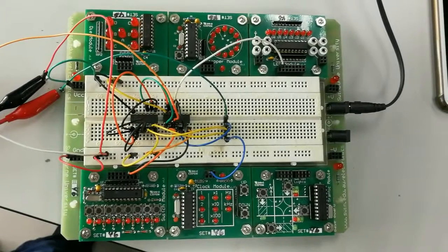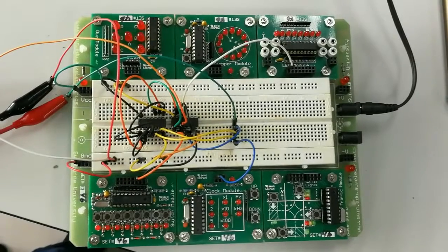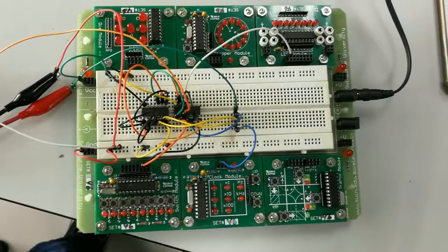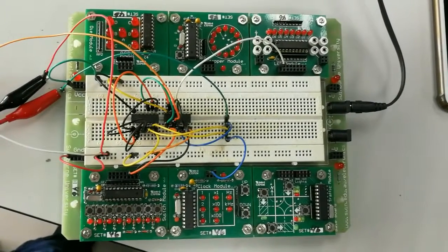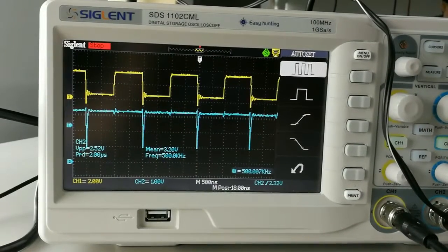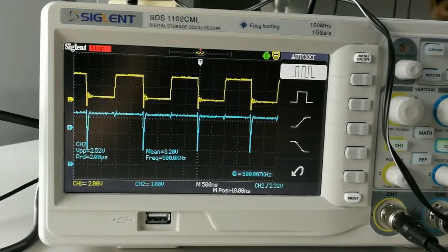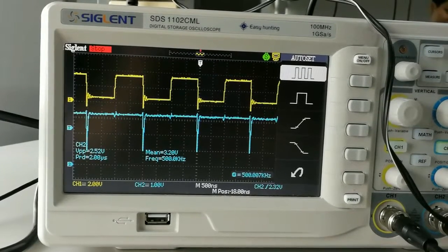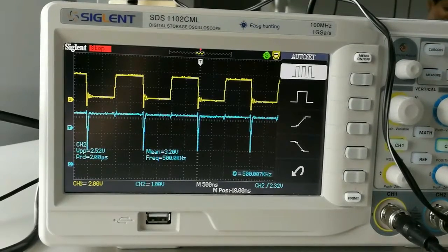We use one 74HC02 IC and one 74HC00 IC. We connected the input to the clock module and the two outputs to the oscilloscope. The following is the display shown on the screen of the oscilloscope. When it reaches the falling edge of the input, the output value will suddenly drop from 1 to 0, and this is the static 1 hazard.